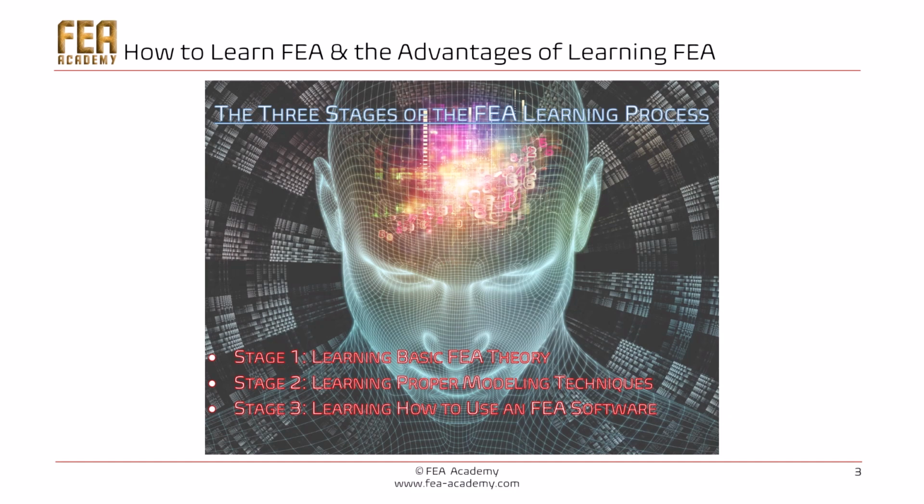There are 3 stages for the FEA learning process. First, learning the basic FEM theory, learning proper modeling techniques, and learning how to use an FEA software. Engineers typically learn FEM theory in university or college before they learn how to use the FEA software. And all too often, they skip the stage 2, which consists of learning the proper modeling techniques.